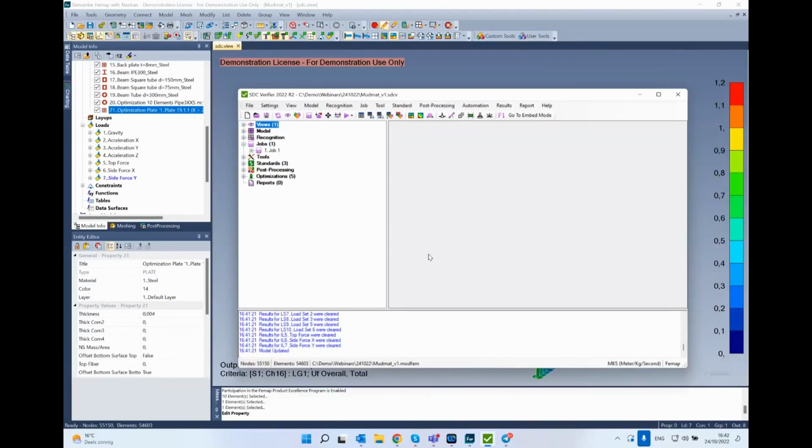I see that you are setting the list of possible thicknesses. For example, for buckling calculations, the SDC Verifier is checking each thickness. Does it fit or not? But can we set the required buckling factor, and the program will show us the thickness which fits this buckling factor?